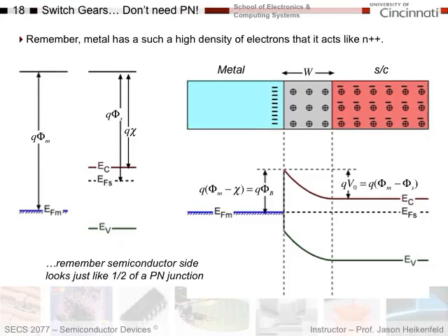Okay, so let's wrap up our first lecture on FETs with a couple other types of FETs. And before we go into these, we need to review some basic concepts. Particularly, the type of FET we're going to talk about next uses a Schottky or metal semiconductor contact to make the gate contact. So the particular case we're going to look at is a rectifying or Schottky contact on N-type material, as you can see here.